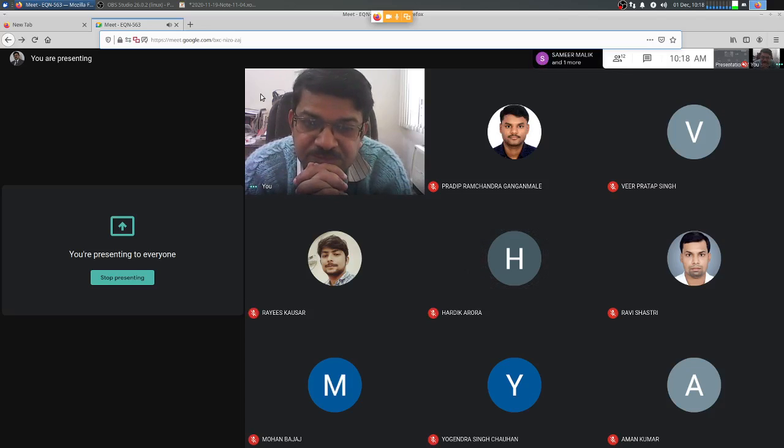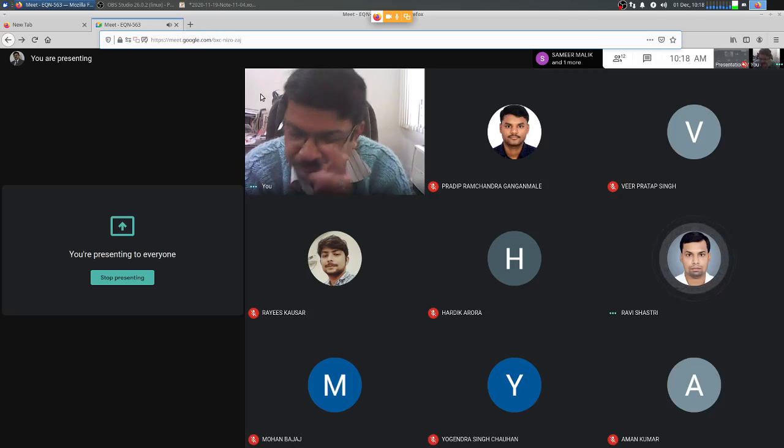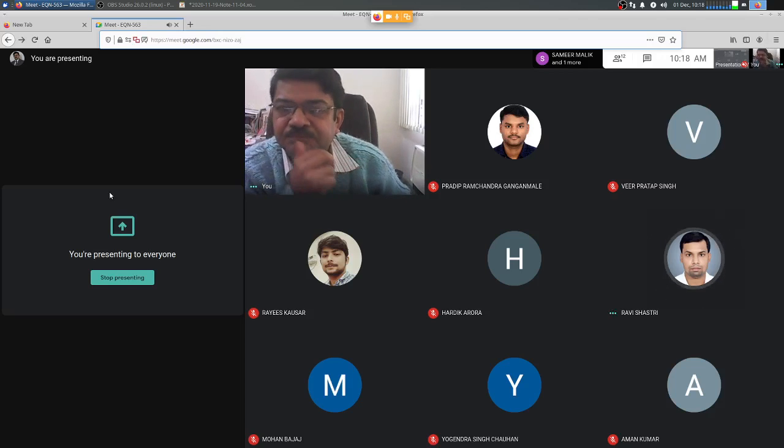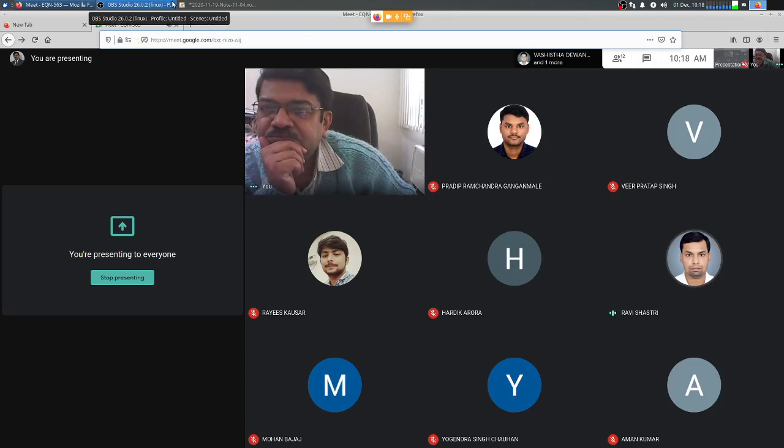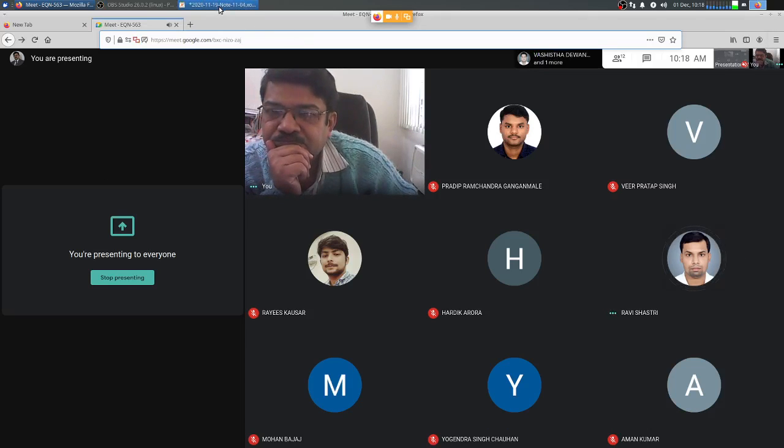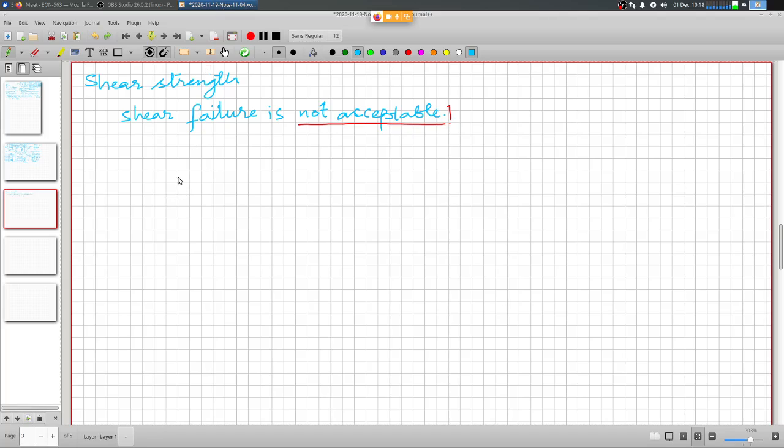Yes. It prevents principal tension, because the maximum shear is at 45 degrees to the principal plane, and some amount of force is resisted by the shear stirrup due to that. So, yes.